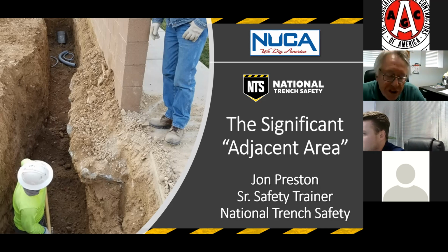The industry standard has evolved to where we translate that to mean no gap more than 4 to 6 inches on each side of the wall. Now, some manufacturers might say no gap is allowed and you have to backfill any gaps. But many manufacturers say a 4 to 6 inch gap on each side and no more than a foot overall wider than the width of the trench shield. I hope that makes sense.